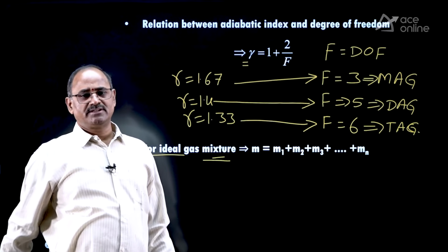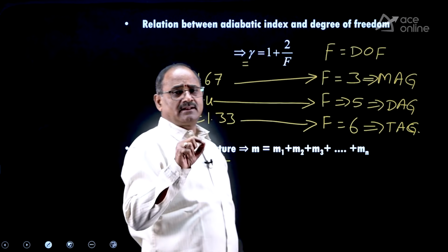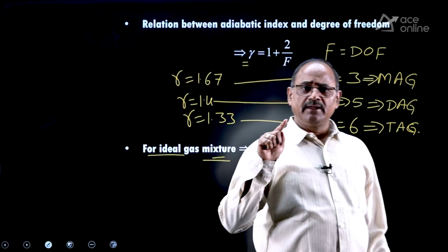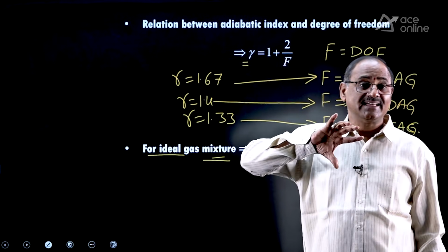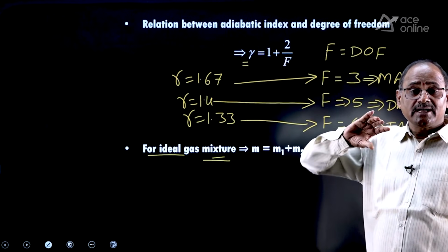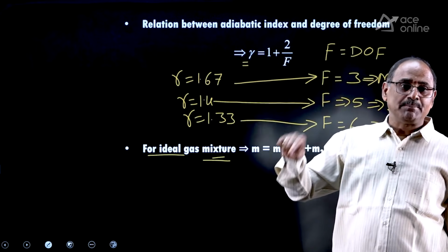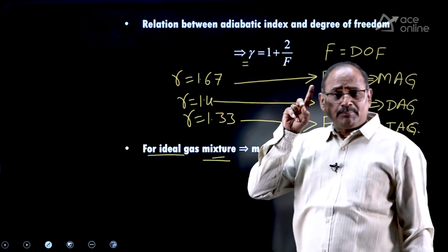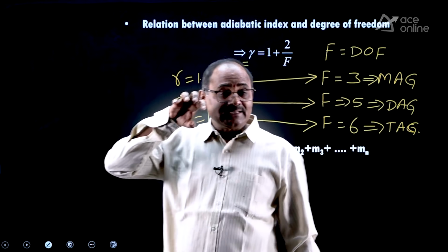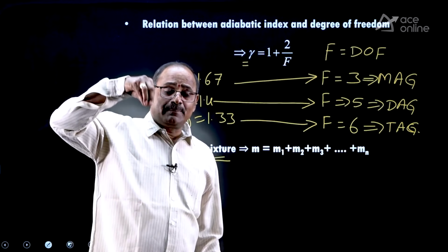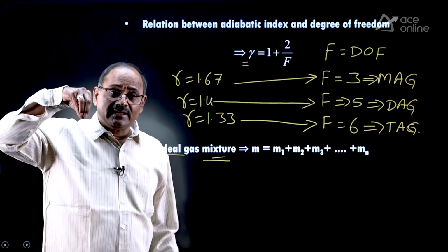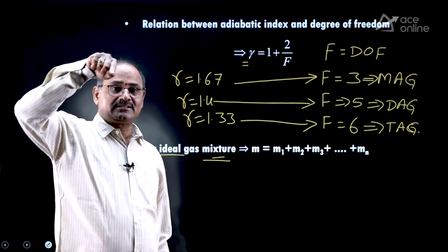Similarly, the mixture of petrol vapor and air particles for the petrol engine, also called the spark ignition engine, is also a homogeneous mixture. Whereas in the diesel engine, the mixture of diesel vapor and air particles is a heterogeneous mixture, because uniform mixing of the diesel vapor with the air is not possible. The main reason is that in a diesel engine, the diesel particles are made to enter the engine cylinder at the end of the compression process.